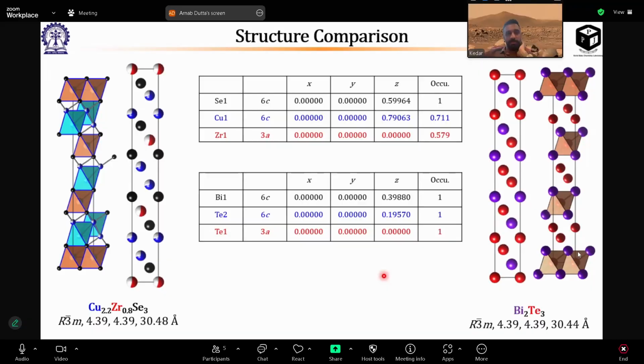Yeah, bismuth antimony telluride is the one prototypical material for all low temperature thermoelectrics. It's basically layered, but the layering doesn't matter. It's a very low band gap, and that's what makes it very good for room temperature thermoelectrics. So that's quite an interesting system. And the thermal conductivity is low. For this structure type, maybe you get low thermal conductivity. I don't know, it's hard to predict. We are at a very preliminary stage of work actually.